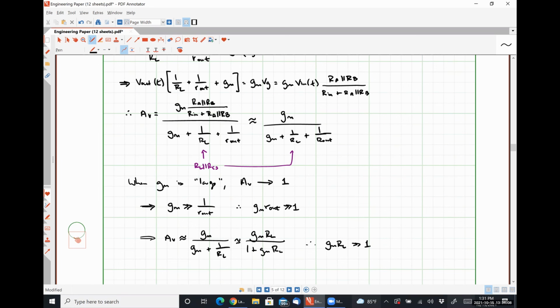So effectively what's going to happen, and we're getting there bit by bit, is that we're going to have a differential amplifier, which introduces some gain. And then we're going to chain that to a common source amplifier, which is going to boost our level of gain. But that gain is only going to be good for amplifying on-chip capacitances effectively. The op amps that we use do have on-chip capacitances, but we're interested in being able to drive signals on off-chip components. And to make that happen, we need this unity gain buffer to do its job very, very well.